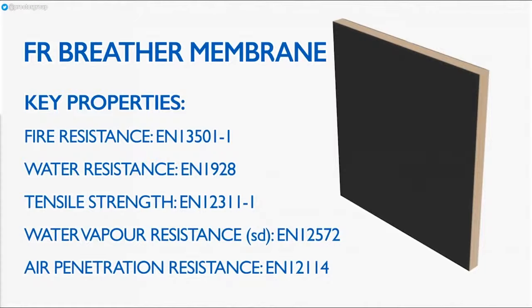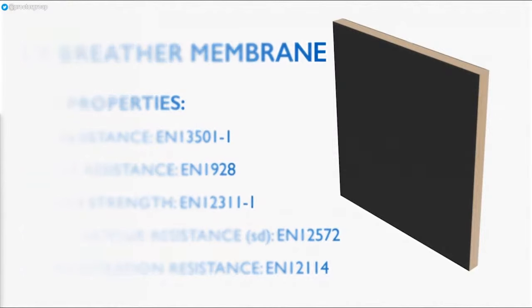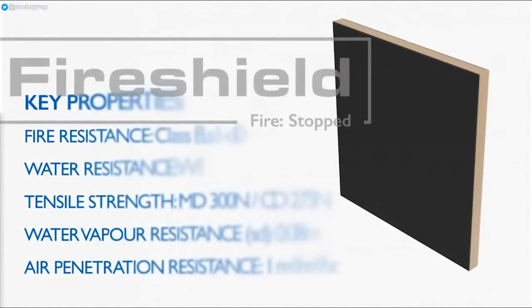The key property in fire resistance is the EN 13501 fire classification, also known as Euroclass. This classification is primarily required by building regulations when used at over 18 metres in height, or 11 metres in Scotland, reflecting the particular importance of controlling fire spread in high-rise applications. It is, however, becoming more common to specify fire-resistant membranes in low-rise applications, going beyond the regulations.